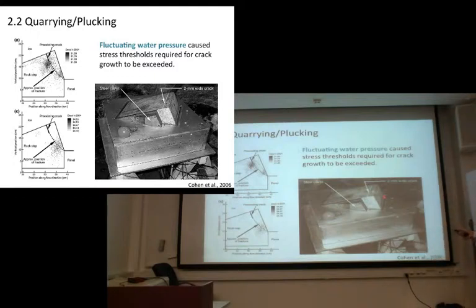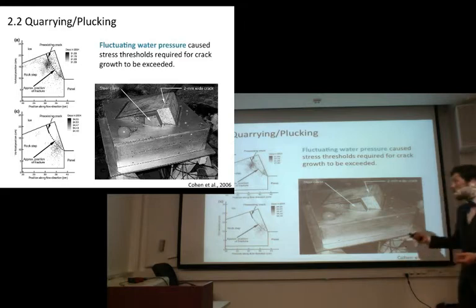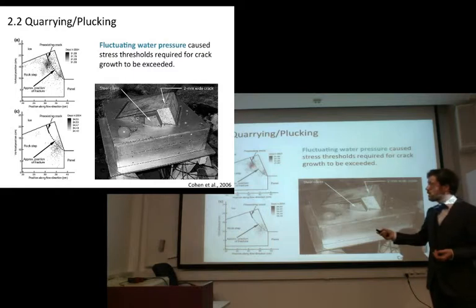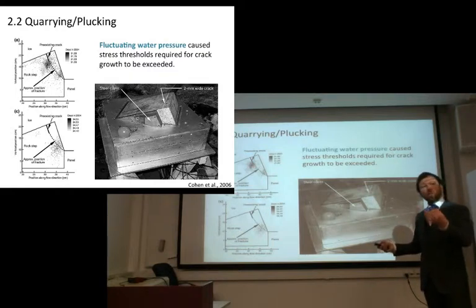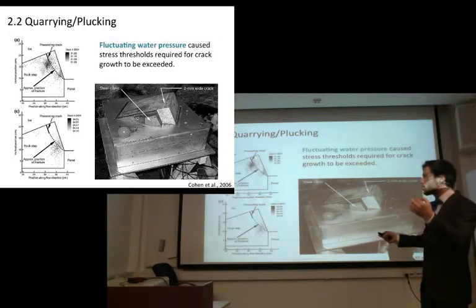And what they observed is that when it was under the ice, they could form a cavity on the east side of this granite. As the cavity was forming, they were measuring the activity of the crack. What you see is the block in cross section and the activity, measured using acoustic emissions. The crack growth is represented by each dot.